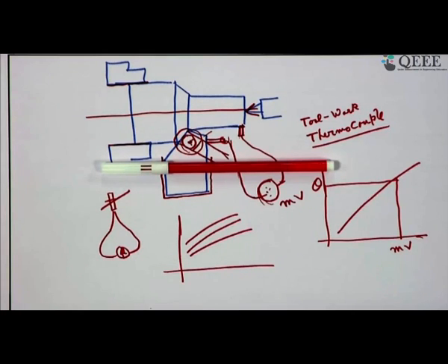Number 3, when it is a forming tool, you cannot use carbide or ceramic to have that particular shape or form on that. So, these are some of those reasons why this HSS tool has to be made, and still it is in use. You cannot 100% discard them. Forming tools, say for example, grinding of the tools becomes a very difficult task with carbide or ceramic. So, if you have an HSS tool, that form you can give there and you can use it rather conveniently.